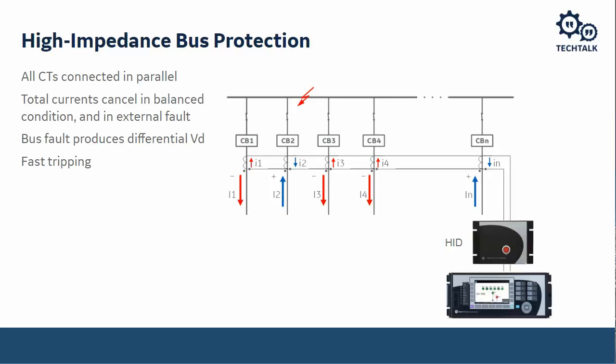The drawback on something like this is that all the CTs need to be identical, and they need to be dedicated, so you can't use them for anything else. In switchgear applications, this is not really feasible because you don't have a lot of space for an extra set of CTs for every feeder in the main. Another consideration is keeping the lead lengths equal from the CT to the relay. This is highly impedance dependent.